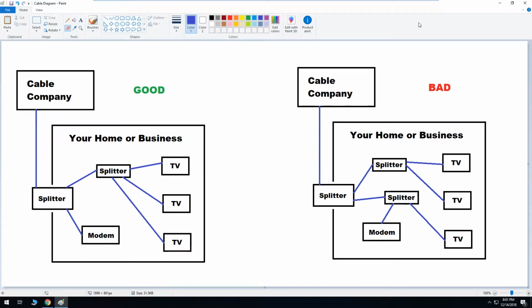If your signal is near or above 15 and you're experiencing internet speed or quality issues, you should take steps to correct it. Your cable company may be able to help. They'll be able to tell if the signal strength issue is coming from something inside your house, like too many splitters or bad cabling. If that's the case, try to reduce the number of cable splitters between your modem and the main feed from your cable company at the side of your building.